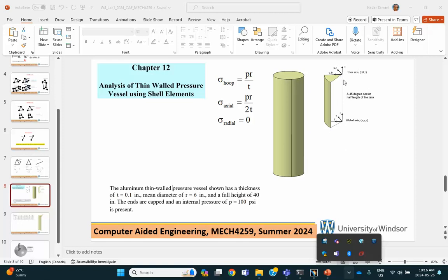The advantage of doing it like that is that when you take this inverted L and revolve it to get the surface, the top and the side are, in principle, a single surface, and therefore when you mesh it, it'll do both of them at the same time. If you put the two-dimensional property on it to specify its thickness, you'll do it at the same time.